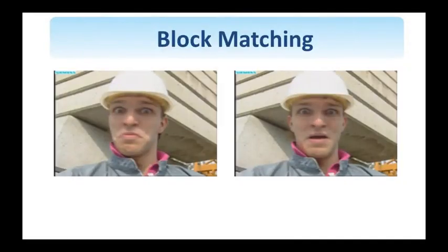Let us discuss now the block matching motion estimation method. This is probably the most intuitive method out of all the methods we are going to discuss. The steps are indeed conceptually very simple. We see here two different frames from a video sequence, the Foreman video sequence. So this is the frame x of t minus 1 and frame x of t. The two frames can be consecutive or can be further apart in time.